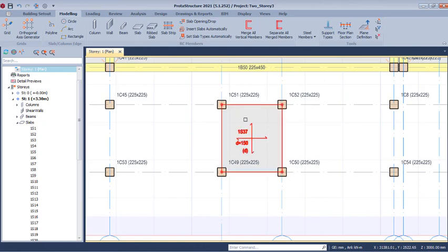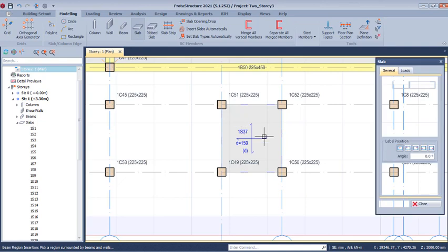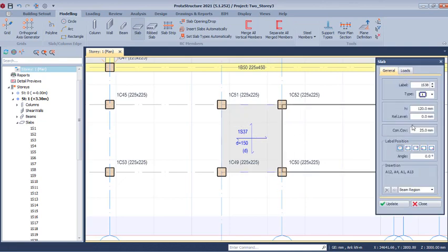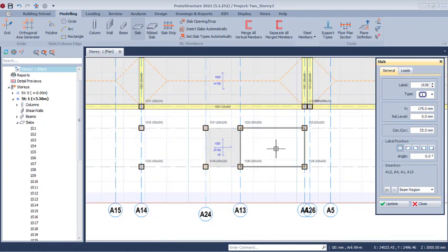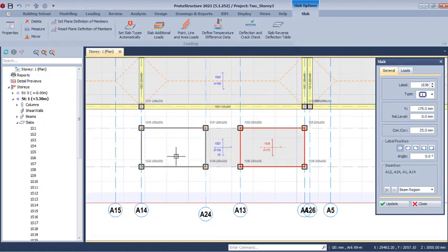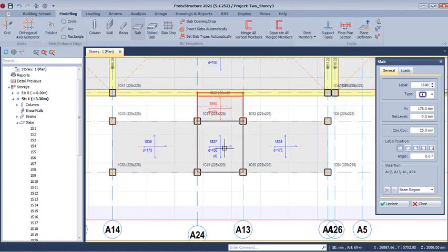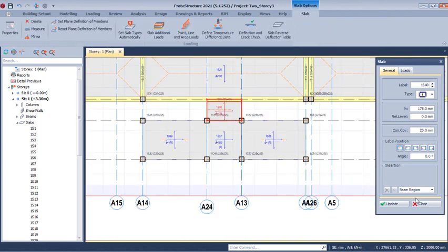for the stairs. So you click on the slab right there. Check these provisions, make sure you have it to be 175 this time around. 175 should be the thickness. So we will have to place it here, and then as well we place it here. We also need it here, that is going to connect to the first floor right there. So we click on the close option.